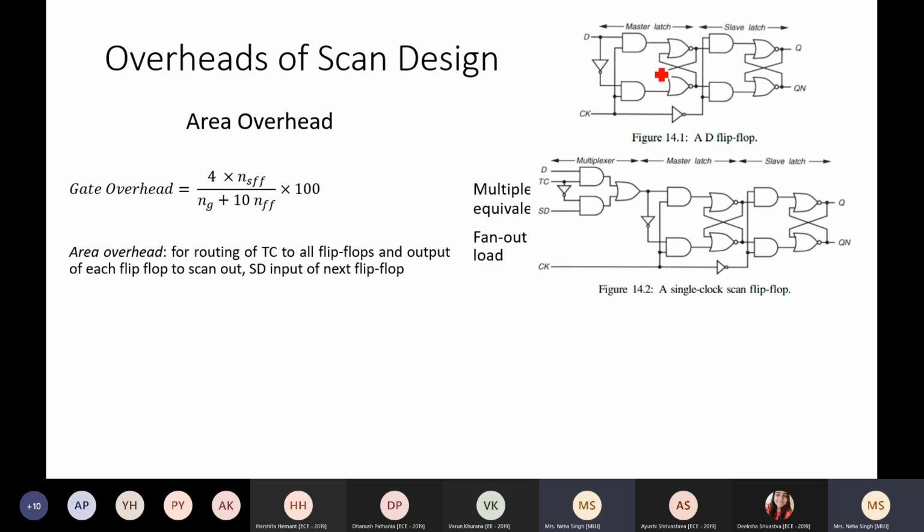So if my master is running at clock equal to 0 or clock equal to positive edge, then the slave will run at negative edge. So that any change which master captures at the positive edge, that change will be taken up by the slave at the next falling edge. Right? So during one clock cycle, the data will be transferred, but with certain delay, so that everything can be settled down at the master level, so that slave can directly read it.